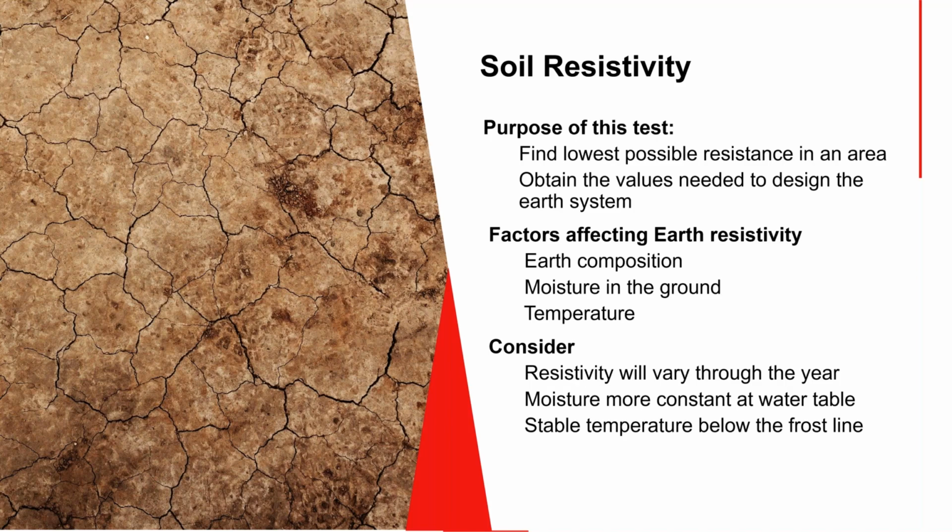Well, for one thing, if you do have the luxury of additional space to work in, if you're making an installation and you want to have the best possible ground, you can actually prospect a piece of ground and find the lowest resistivity, which would be the best place to install your ground.